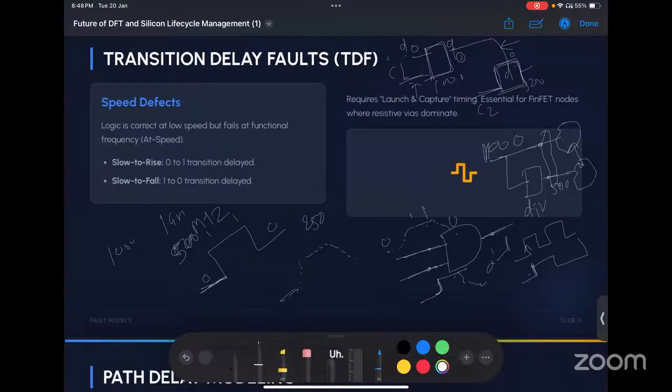Again, one more thing. Ideally, in every functional path we have one extra delay here, right? Because we're adding one flop here. In some cases there are flops, in some cases not. But there's a penalty here, like one extra cycle in the functional path also. So we'll be covering this particular node also.